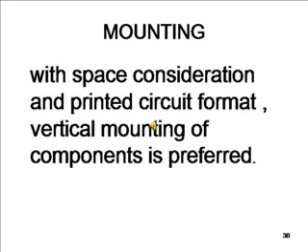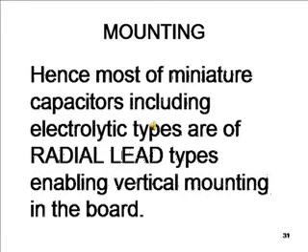With space considerations and printed circuit format, vertical mounting of components is preferred. Hence, most miniature capacitors, including electrolytic types, are of radial lead type, enabling vertical mounting on the board.